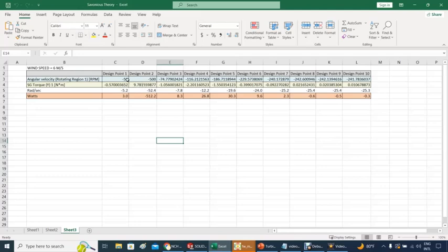So you know that there's a value of RPM between these two that will be 0 torque, which is this one here, about 0 torque. And that gives you about 242. So this turbine will do free spinning at 242 at a wind speed of 13.6 miles an hour, or 6 meters per second.